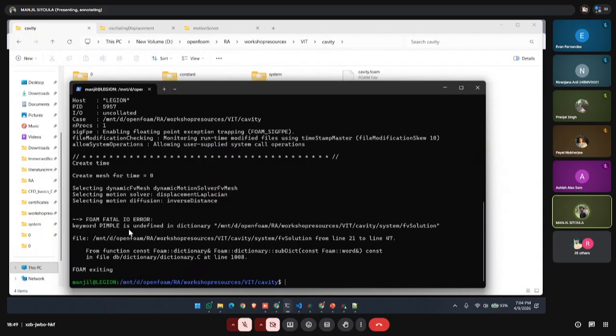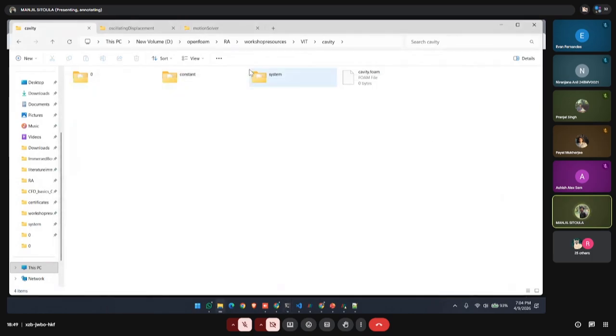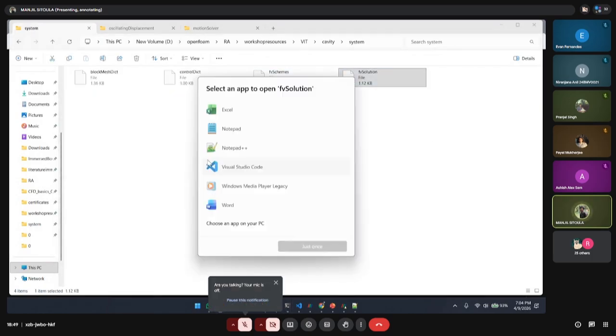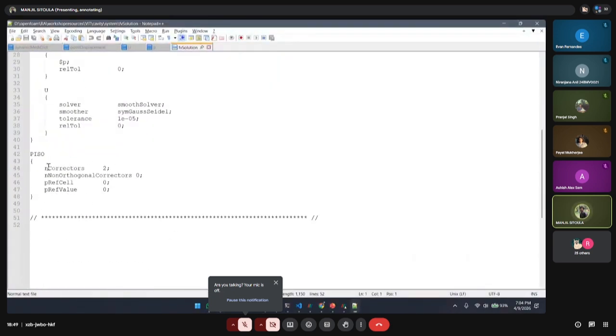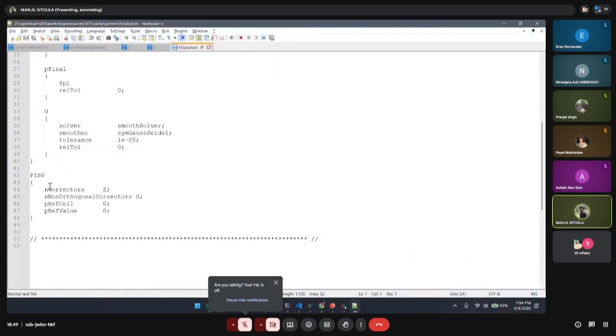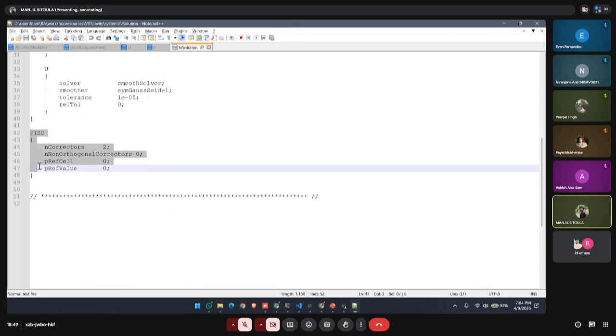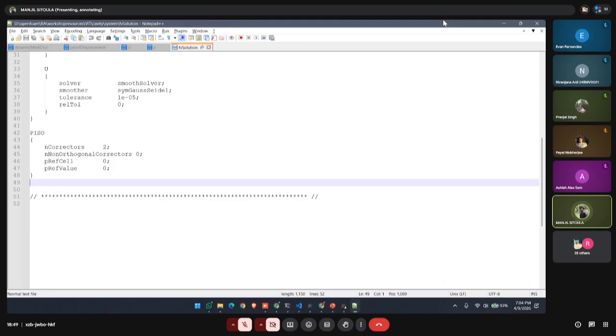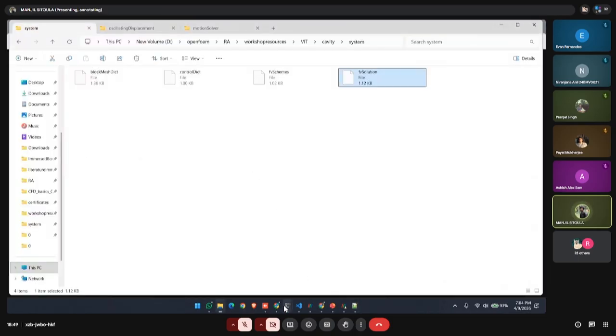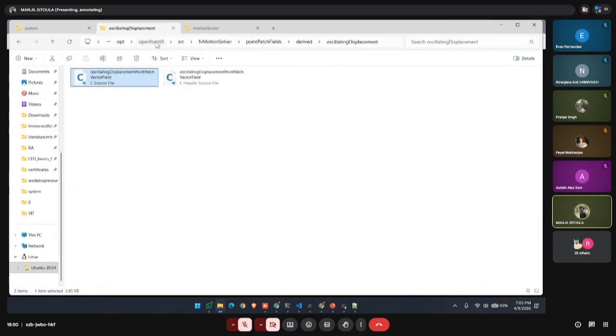It is saying keyword pimple is undefined in our dictionary fvSolution. So if you go to the fvSolution, it is searching for the PIMPLE algorithm, but we don't have it defined yet. So based on our error, we need to debug it. Let's go again to our tutorial case.